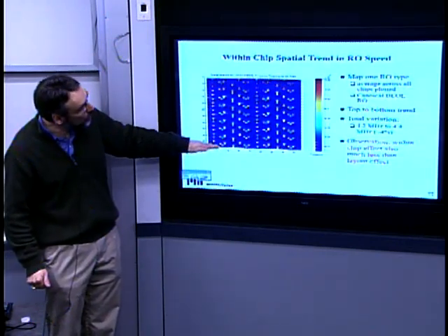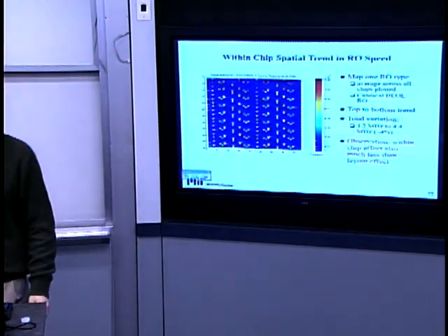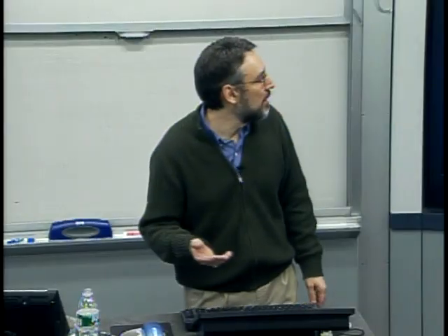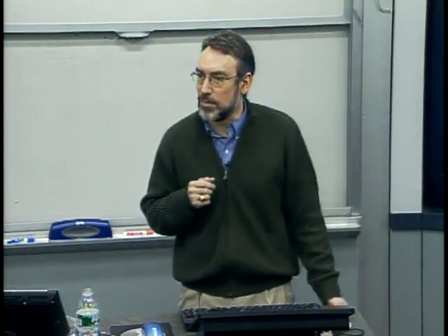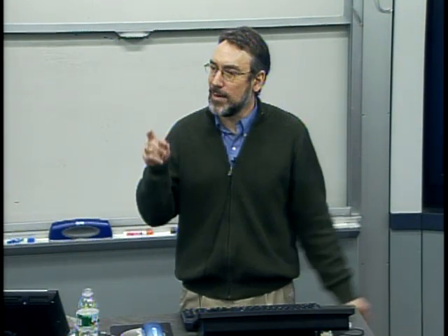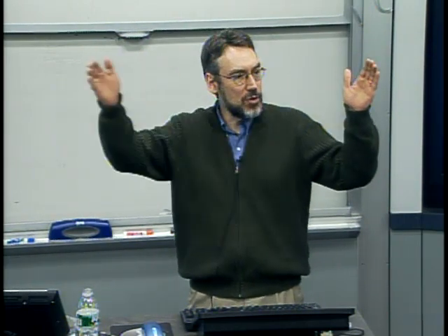And here again, you can see a top to bottom variation in the ring oscillator speed. And in this case, that within each individual chip is about 4% in this particular case, which is quite interesting. Notice we said there's 9% across the whole wafer. And I might have 10 chips lined up sort of in a line across the wafer.